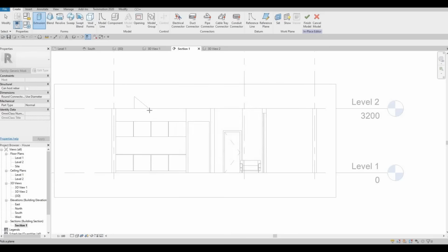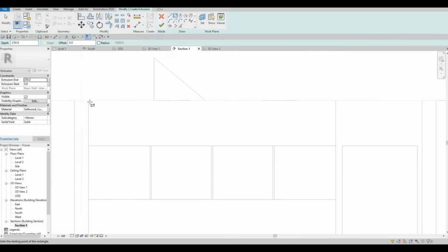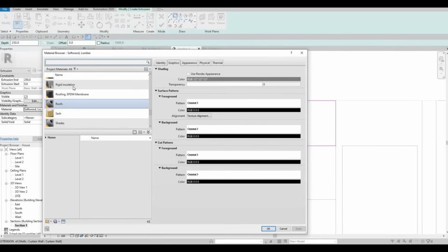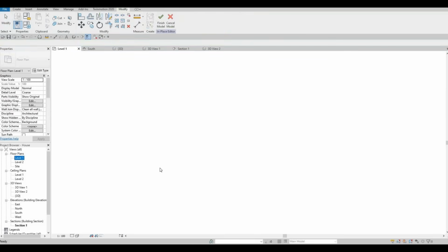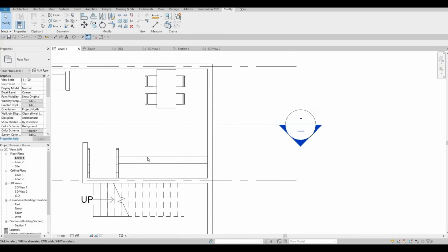Pick a plane, it will be the wall, and then click rectangle, and then now we just need to change this material. So let's use roofing. So I'm picking the materials randomly, so you don't need to do that, but I want to make sure that this is all different so that once I've finalized the material, I could change it more.